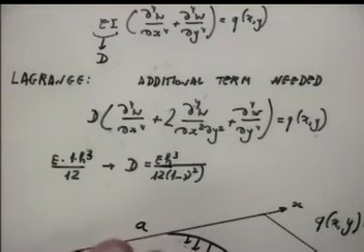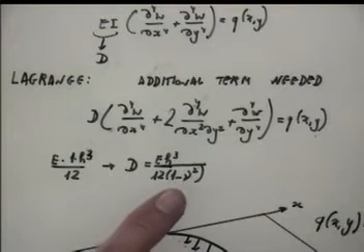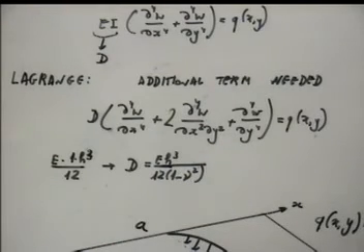That means that plate equations do not automatically reduce to the beam equations because there is this Poisson effect. Indeed, plate is something that has two directions, and these two directions are interacting. They are dancing together, so to say. Because they are dancing together, Poisson ratio should be there. Because Poisson ratio takes into account interaction of x-y directions.